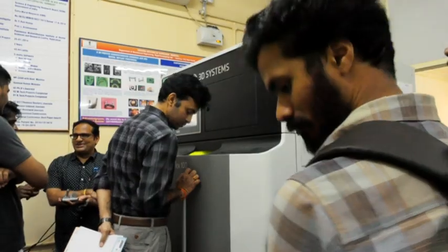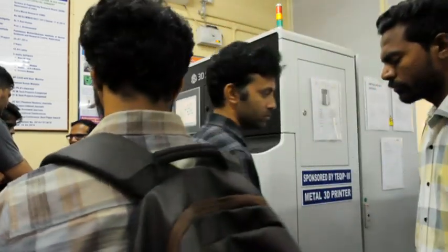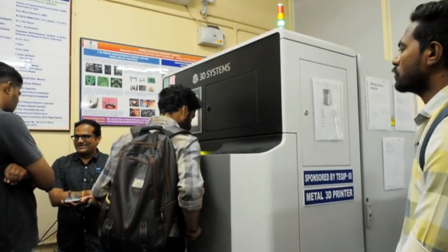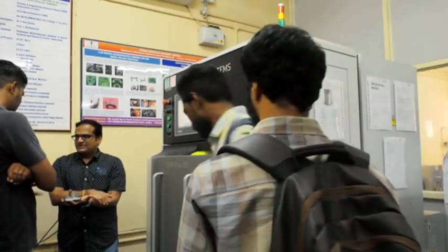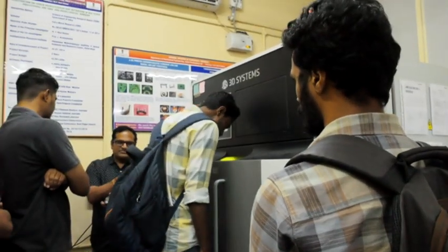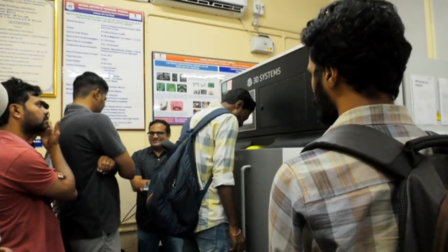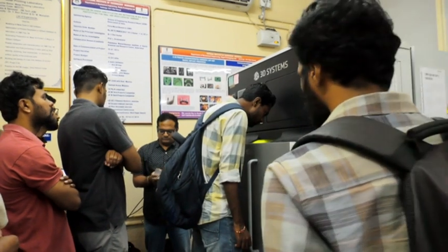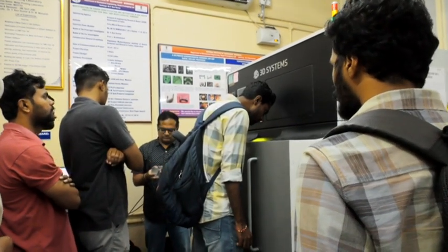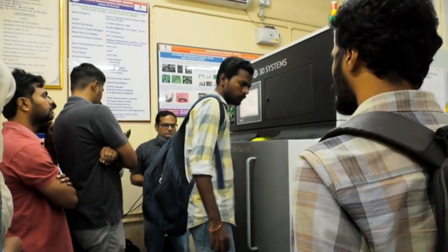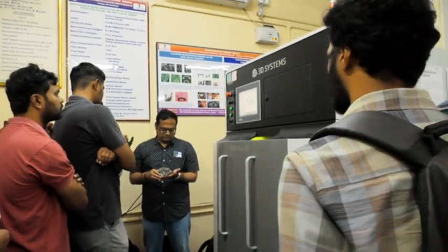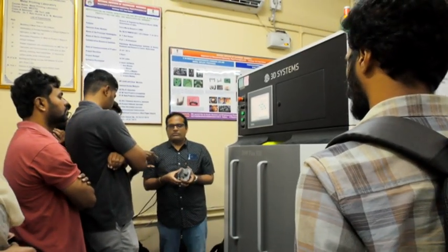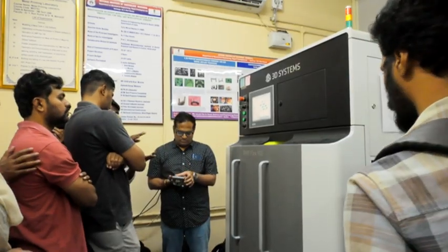10 kg steel is not costly, but 10 kg titanium is very costly. What if the titanium build has mistakes, right? Then we can even reduce the quantity of titanium, around 5 to 6 kgs. Because you have to follow layer height, then volume. Mass will be density times volume, right? Here volume will be suppose 100 into 100 into 8. Then you can get the mass, like how much quantity you have.